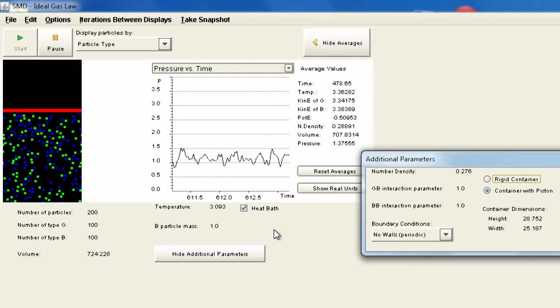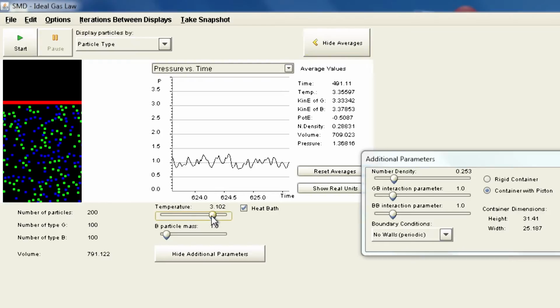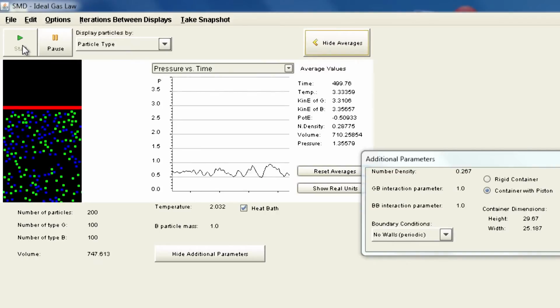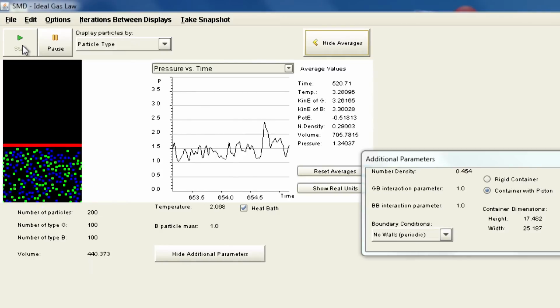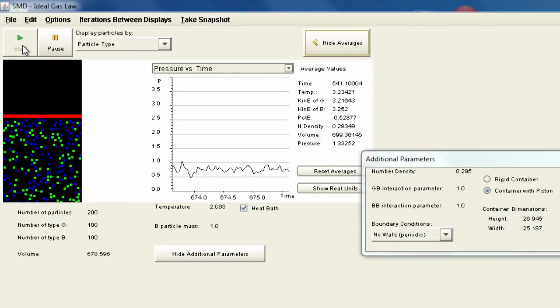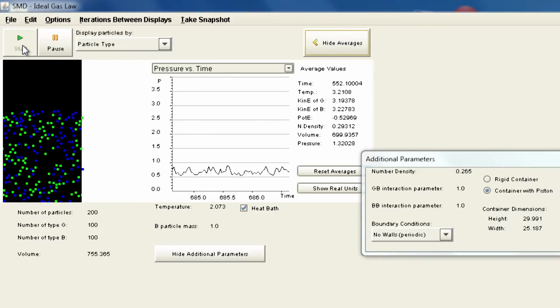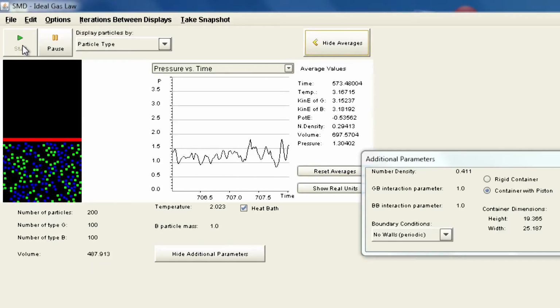Now, in order for me to change the isotherm, what do we have to do? We have to change the temperature. So, we are going further down, because we are at the limit of it, and we will observe both the heat taken out as well as the constant pressure kept on the system. Now, again remember, you have to give it some time for it to come to the equilibrium situation. So, now we are coming to the equilibrium situation in isobaric, and as you know, it is going to fluctuate, which is a good demonstration that you should wait for the system to get to equilibrium situation.